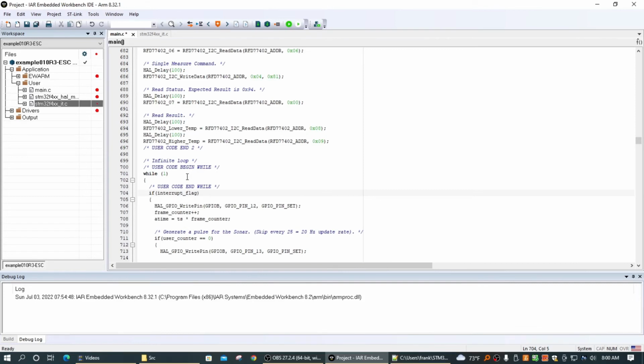So the way this works is an interrupt flag that the timer 3 when it runs out sets. So this part only runs when the interrupt flag is set to 1. Now at the very end it sets it to 0, so it just goes in this while loop and skips out this part until you get the interrupt with the timer, and then it restarts this again.